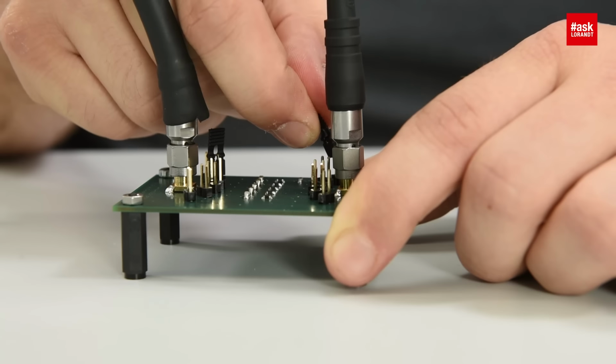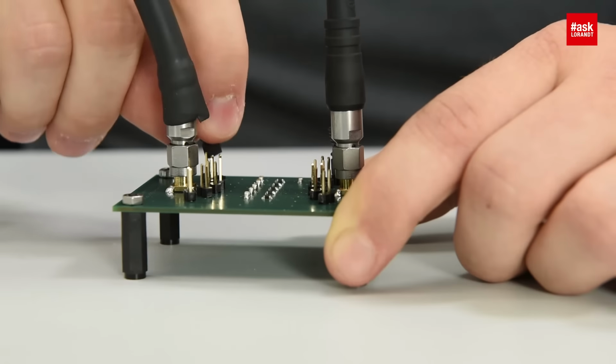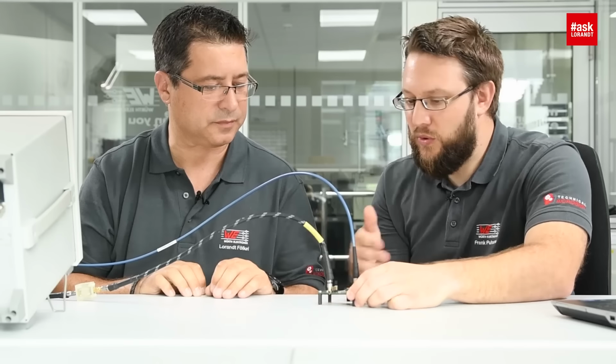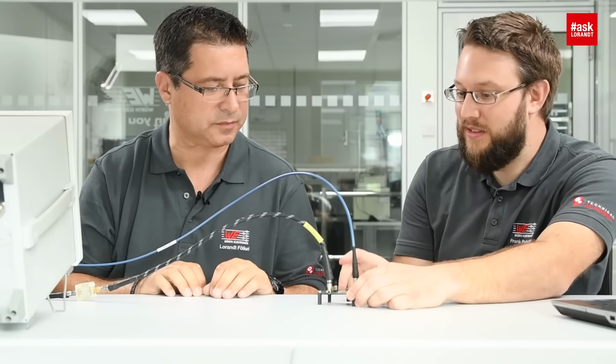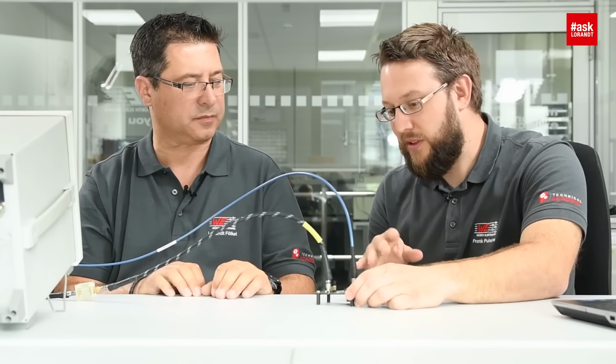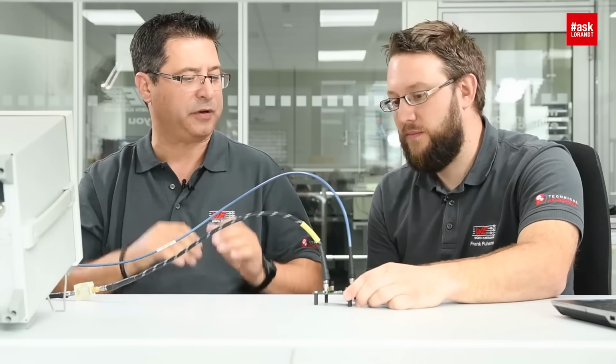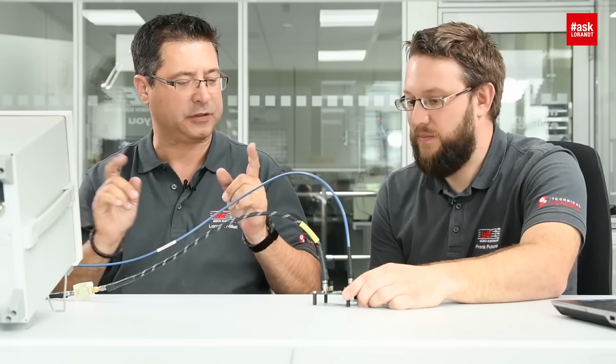At the end, the pi filter with 1 microfarad, 6.3 volt, to show that because we halve the capacitance value because of the pi structure, the influence is less, but the filter resonance frequency stays the same. So the pi filter has 2 capacitors, each 1 microfarad.